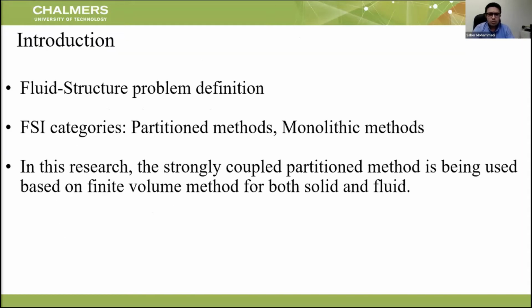A fluid structure problem is defined by a set of governing equations to be fulfilled in the fluid and solid domains, plus suitable coupling conditions, ensuring the continuity of velocity and normal stress across the fluid-solid interface. We can divide FSI problems into partition methods and monolithic ones.